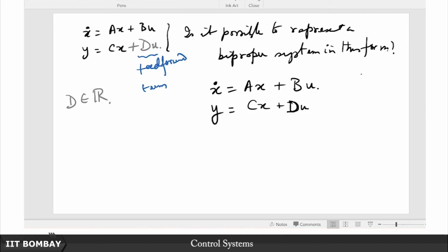By the way, in MATLAB there are the commands SS to TF and TF to SS. You should try them out, read their syntax. If you describe a system in terms of state space and you want to see its transfer function, then you have to use the SS to TF command, see what its arguments are. This could be a nice exercise for you.